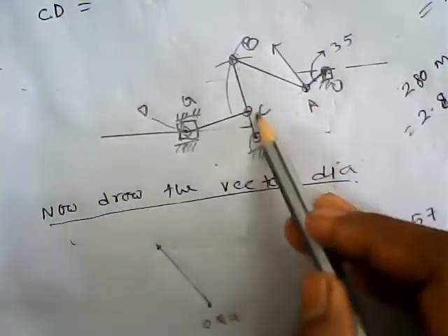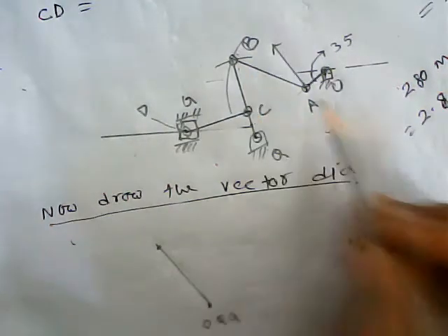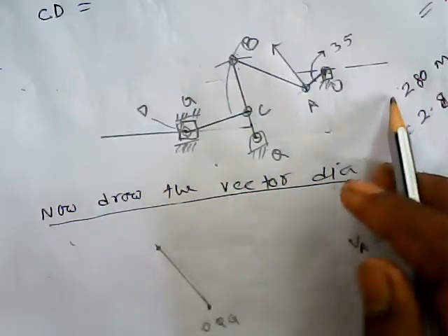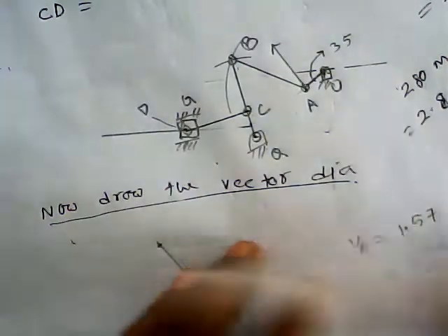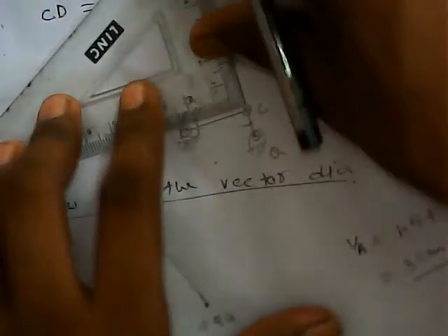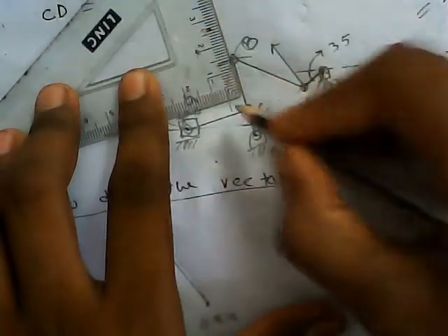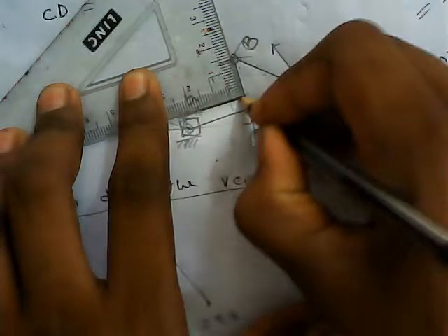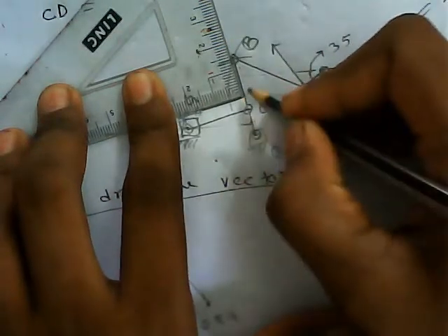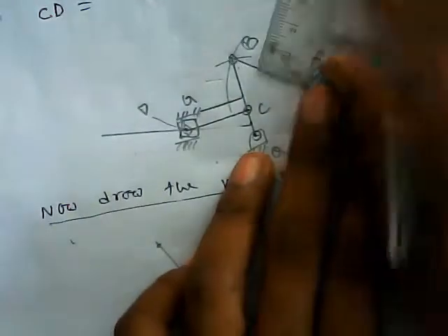Now the velocity at the point B, which is passing through C and A, where they intersect, that is the point B velocity. So velocity of point B with respect to C, which is passing through C, is perpendicular, in the perpendicular direction along QB.